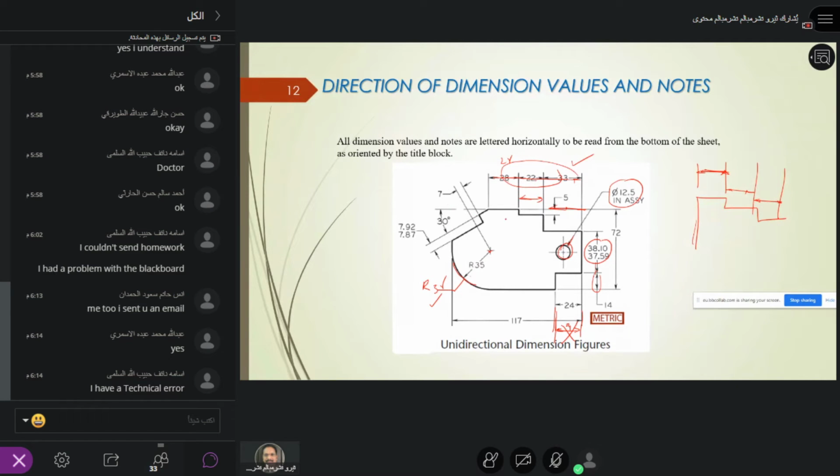And a slope, or an inclination. So with the horizontal, it makes 30 degrees. See how they did it? And they draw the parallel lines with this dimension and extend it with dimensions. So this is a very good example of how to put the dimensions for a technical drawing.